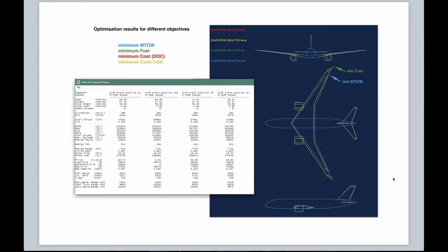In lecture 6 we chose to use MTOW as the optimization objective that we wanted to minimize, but of course there are alternatives. This slide shows an older example study that looked at some alternative optimizations based on different objectives. Now, talking about design decisions and optimization philosophies opens up a gigantic Pandora's box, but for large long-range aircraft such as this, simply minimizing the MTOW is likely to give a well-balanced design solution. And that is what we already discovered in our case with the lecture 6 plane.